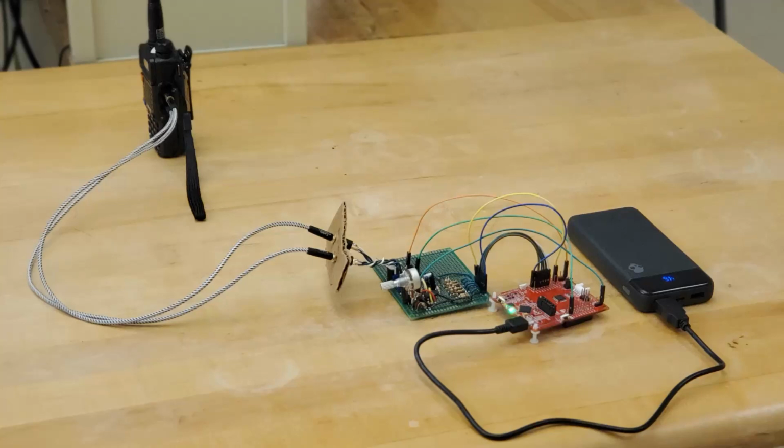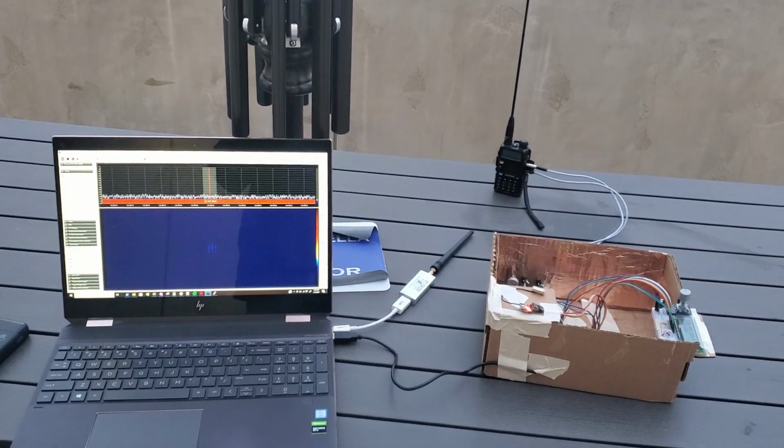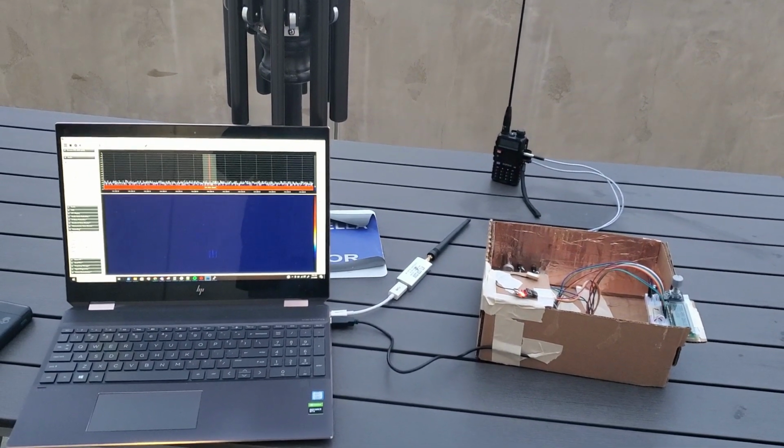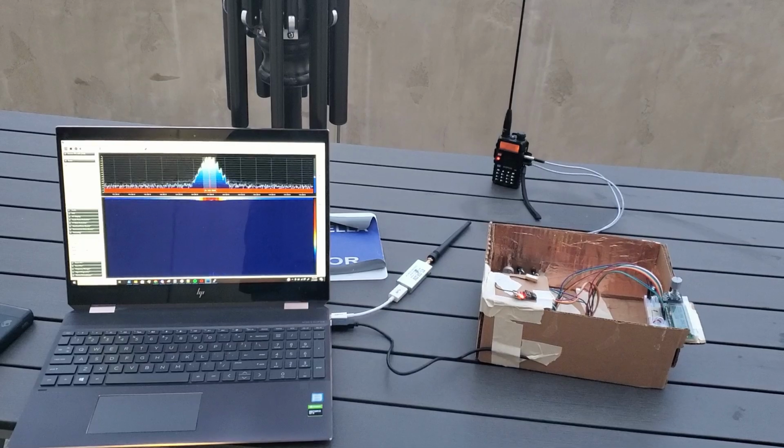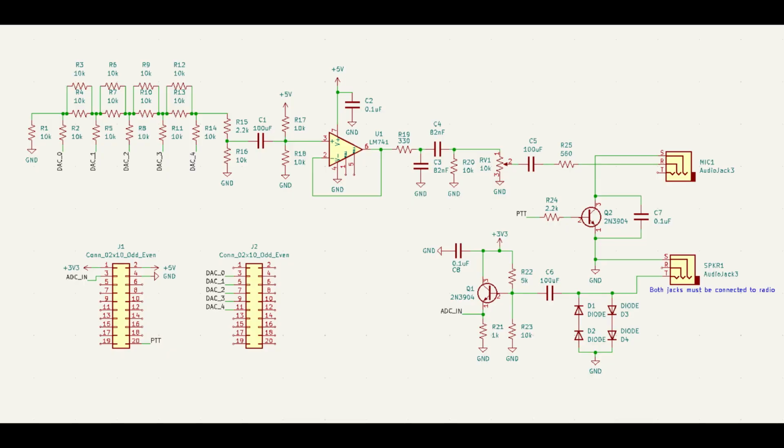Hello, this is a demonstration of the Packet Radio Bulletin Board server that I made as my final class project for Professor Vahid's CS122A class at UCR. This project builds upon my last project, where I used an MSP430 microcontroller to modulate AX.25 packets. In this project, I undertook the much more difficult task of demodulating packets and using that functionality to create a server that operates using amateur radio instead of the internet.